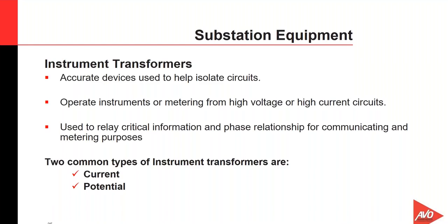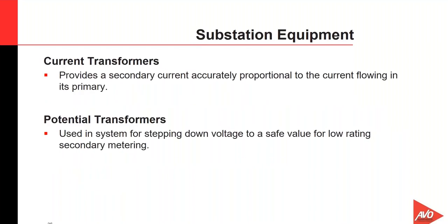With our potential transformers, okay, in theory, really all a potential transformer is just a step-down transformer. Okay, it has a higher turns winding on its primary than its secondary, of course, and they're designed to present minimal load to the supply being measured with an accurate voltage ratio and phase relationship to allow secondary metering. So they're going to give us that opportunity to see what that voltage is on the secondary side, and find out where our substation is really at within the grid.